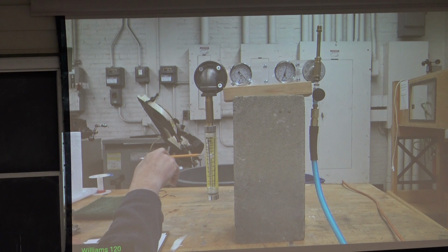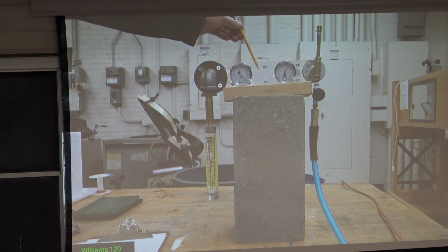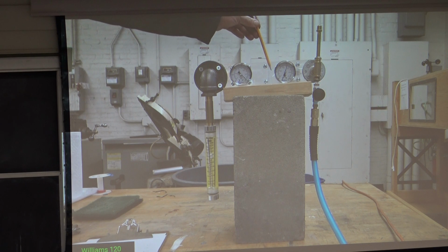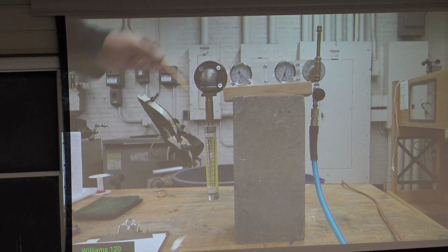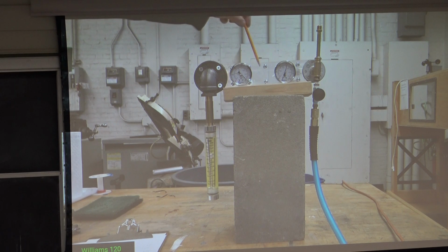And I'm still right at 0.71. So I now have sonic choke flow right at that restriction, moving Mach 1. And no matter how much I bring this pressure down, I will not get any more flow going through this device, because I'm choked right here at the narrowest point.